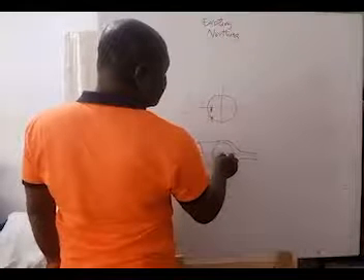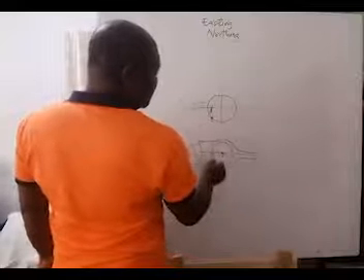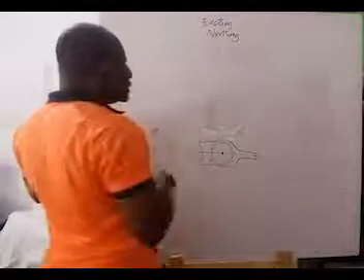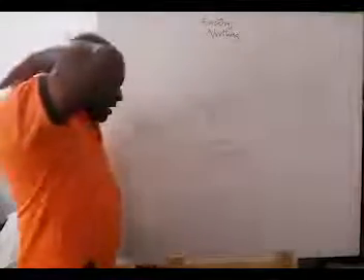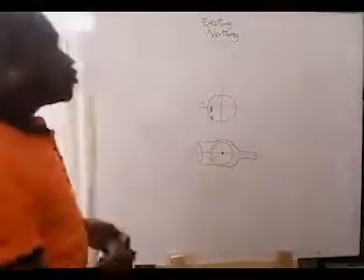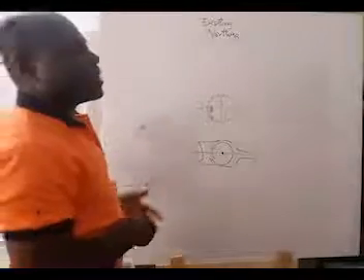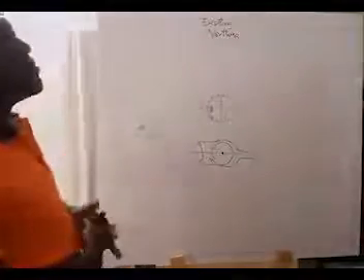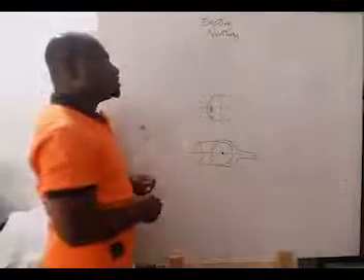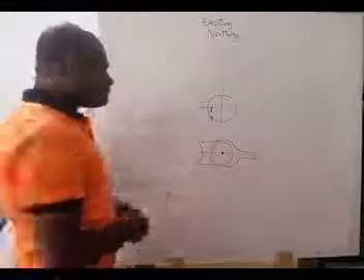As you rotate about the horizontal, the angle changes. The same way as you rotate about the vertical, the angle changes. So that's how it's able to get the angles. It's able to take angular measurements and then use them to compute. The angular measurement is the same as the bearing. It takes the bearing from the angular measurement, and then it takes the horizontal distance from the EDM measurement. It's able to compute the coordinates of points. So that's basically how the total station works.